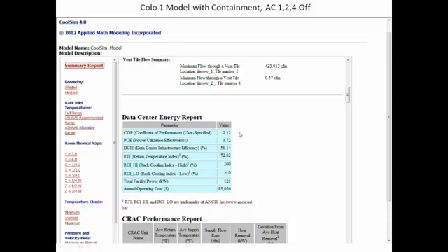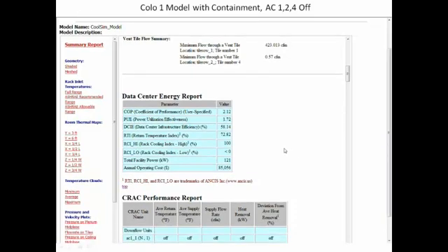The first thing I always do is go for RTI. Try to get the airflow set so that the amount being required by the racks is equal to the amount being delivered. If you can get RTI to 100%, make it exactly the same, you'll optimize the efficiency of the heat rejection system. But the trick is, just because you're blowing 10,000 CFM, Liz, right, it doesn't mean it's going to get to where you need it to go. That's exactly right. Doesn't mean it's going where it needs to go. That's why you need CFD. Exactly. CFD tells you where it goes. And so here we see RCI high is 100 and RCI low is still less than 0 because we're cold.